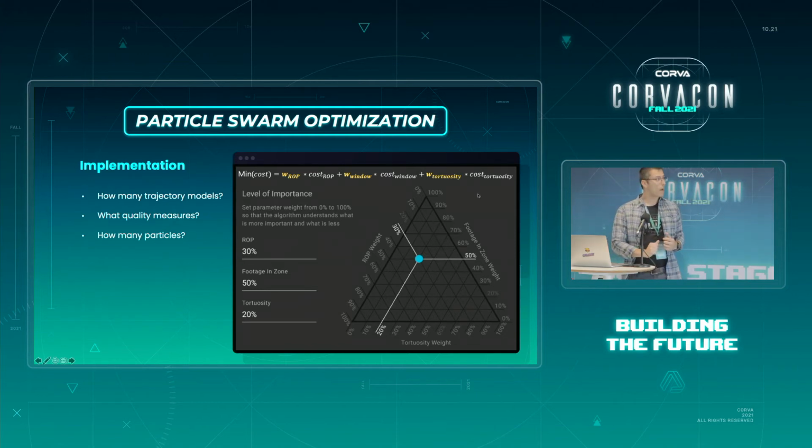And lastly, we have the tortuosity variable, which is how tortuous the wellbore is. That is important because we want the well to be as straight as possible so you can run tools inside and avoid drilling problems, hole cleaning problems, and things like that. We first developed this equation, and you can see the yellow terms are weights for each objective. We did that because we understand that customers may have different objectives depending on where they are in the well or in different wells.